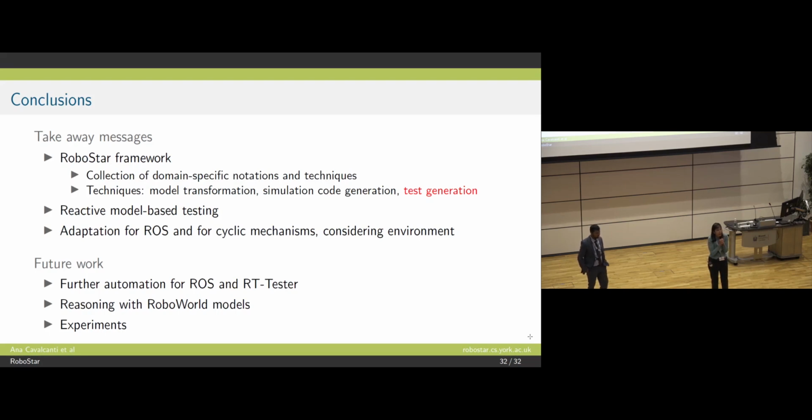What I mean by, I think perhaps interrupt-based is more accurate to say. So what it means is that when the robot is in a particular state, it's not polling anything. It doesn't have that cyclic behavior of a simulation, right? A simulation has an idealized paradigm. Read all the inputs, do the processing, provide outputs, wait until the next cycle and go again. A cyclic executive is like that. A reactive model is not based on polling. I'm there in my state, an input arrives, I note it, I change my state. That's what a reactive model means.